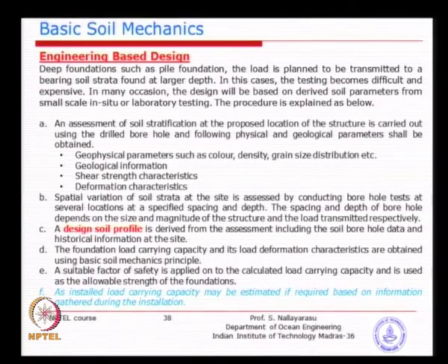Because we could not do the testing, we rely highly on the engineering design. You can imagine that if they had done 4 boreholes at the 4 corners, that would have been slightly better, but somebody wanted to save money and said we do not want to do 4 boreholes, we will just do 1, and it still continues to be done in a similar fashion. We do not want to do 4 boreholes because it is time consuming. Every borehole will take 3 to 4 months to do, plus the laboratory work and writing the report. So, again, there is always a risk when you are designing a foundation for offshore structures. The risk is higher compared to onshore structures, because you are not doing a pile load test.